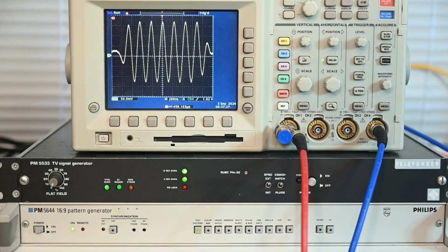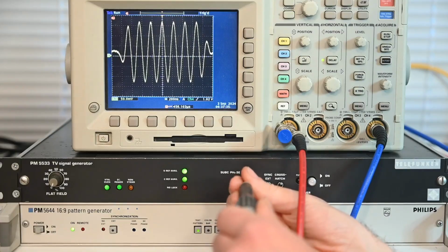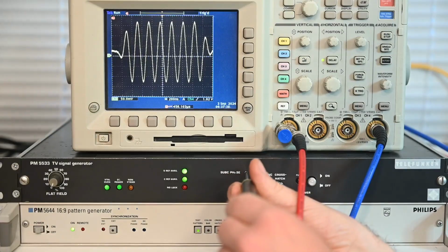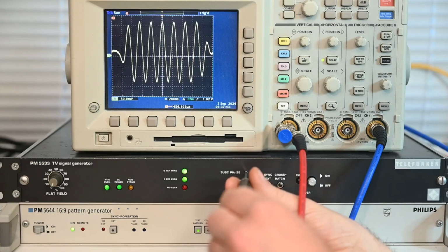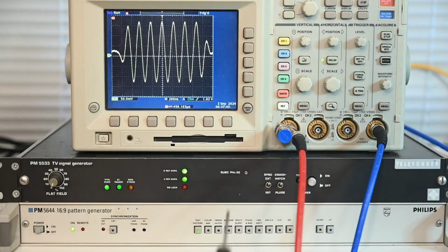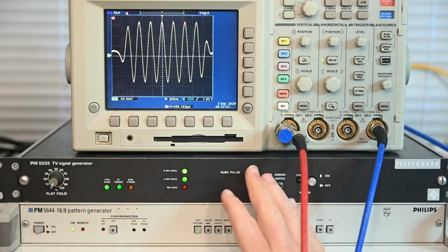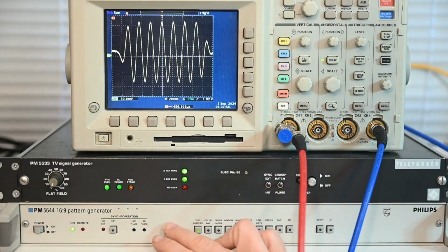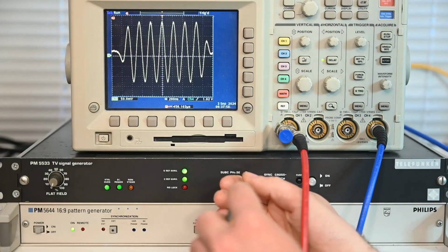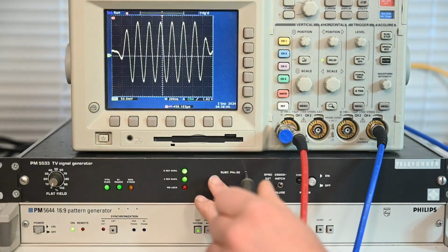Now this is actually a great opportunity to talk about what the subcarrier phase control does, which you will find on certainly a lot of old analog studio equipment. So if we trick this pot here, we can see that the phase of the color subcarrier is actually rotating. And it's rotating in relation to the phase of the subcarrier which is coming from this unit here. So that's really the purpose of it, is to adjust the output of this generator relative to this one, and that's probably all that this control will do. If this were free running, you'd probably find that this pot here doesn't do anything at all.